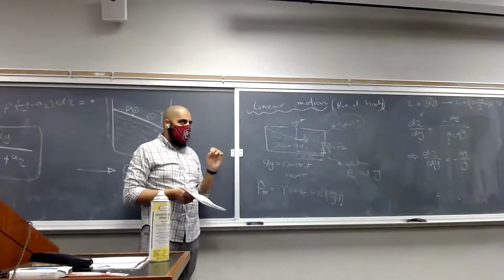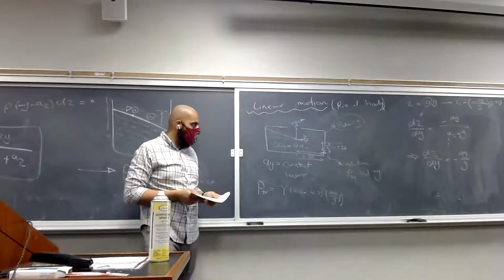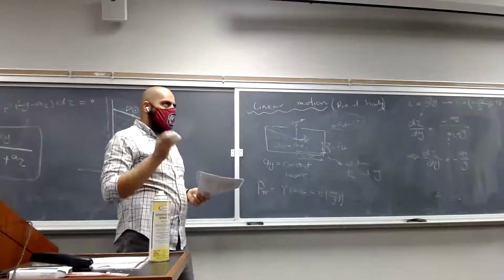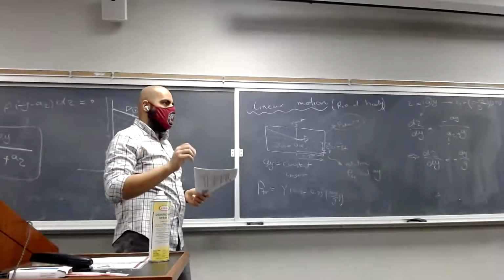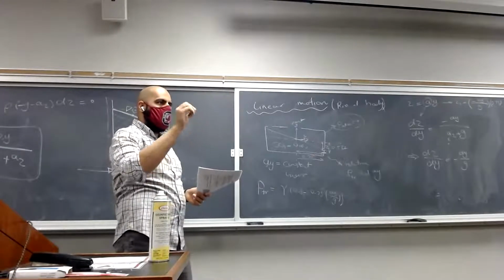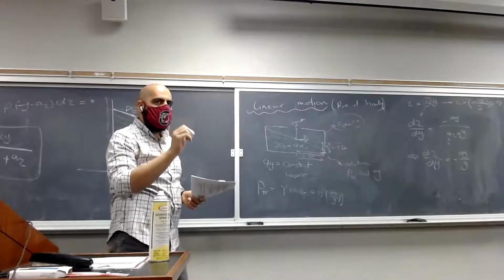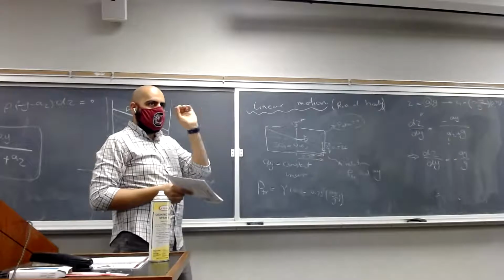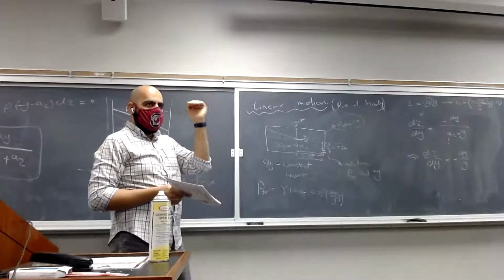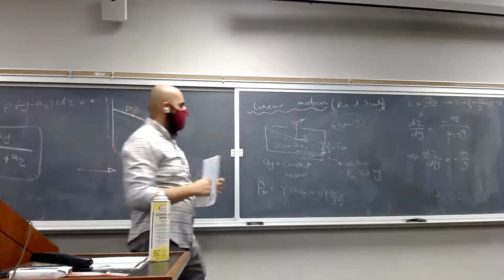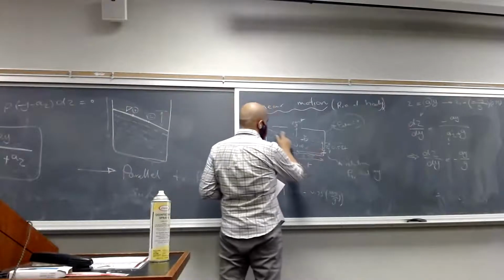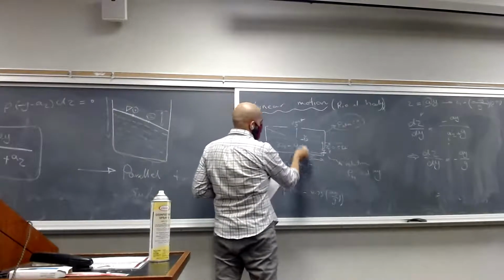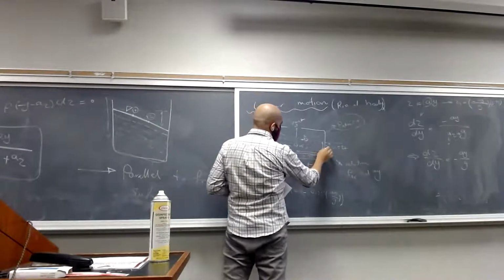We want to find the value, the maximum acceleration we can have before the water level drops below the transducer. So we have to find that specific value at which the water level is at the transducer, right? So the free surface is like this at the transducer.